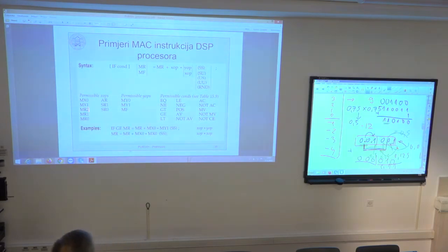So either one of the 2 dedicated input registers or one of the 6 result registers. Then for the y argument, it can be my0, my1, or feedback. So 3 combinations. Again, I use 2 bits to specify the y side argument.